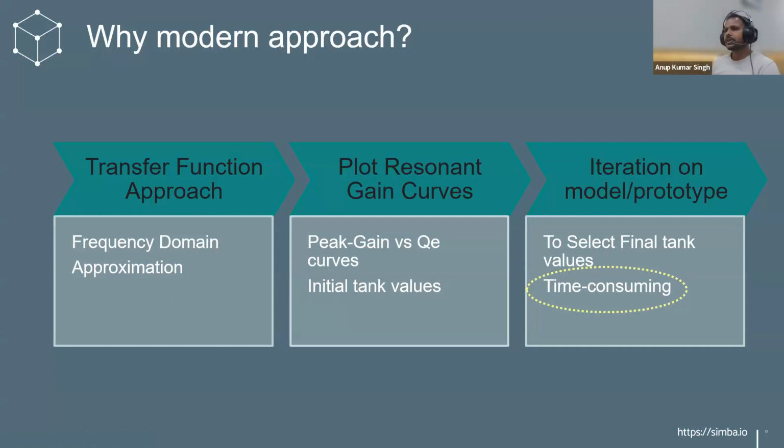But in actuality, in the time domain, it is a switched model, so the input to the resonant tank circuit will be square in nature. If you operate the circuit at the resonant frequency, it will be exactly the same as the approximation you made. But to handle line and load regulation, if you move away from the resonant frequency, the curves will deviate. So there comes the iteration.